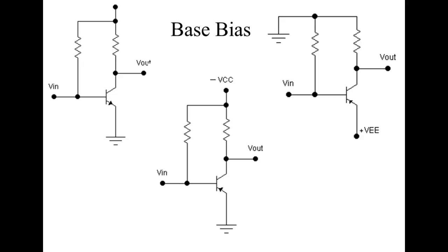I was reading an article about a new type of transistor we call an insulated gate bipolar transistor, and when they first started developing it, that was the problem they had, that it was going into thermal runaway. And now we understand what that is, right? If we design a transistor switch right, then we basically don't have to worry about thermal runaway because we use the minimum beta and the collector current can't go up because it's saturated. Y'all understand what I'm saying?